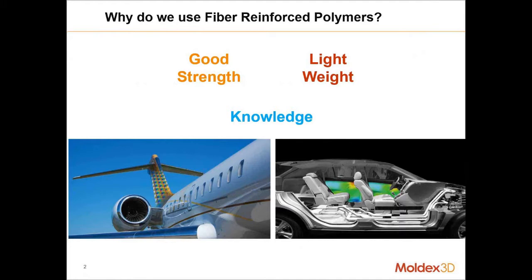So when we're trying to pull the material along the axis, if the fiber is aligned in that axis, the fiber itself is not able to stretch, whereas the polymer would be able to. So you get a much higher strength modulus versus a material that does not have fibers in it. And another main reason for using fiber reinforced polymers is because the material is actually displaced by the fibers themselves. So it decreases the weight of the part in addition to increasing the strength of the part.